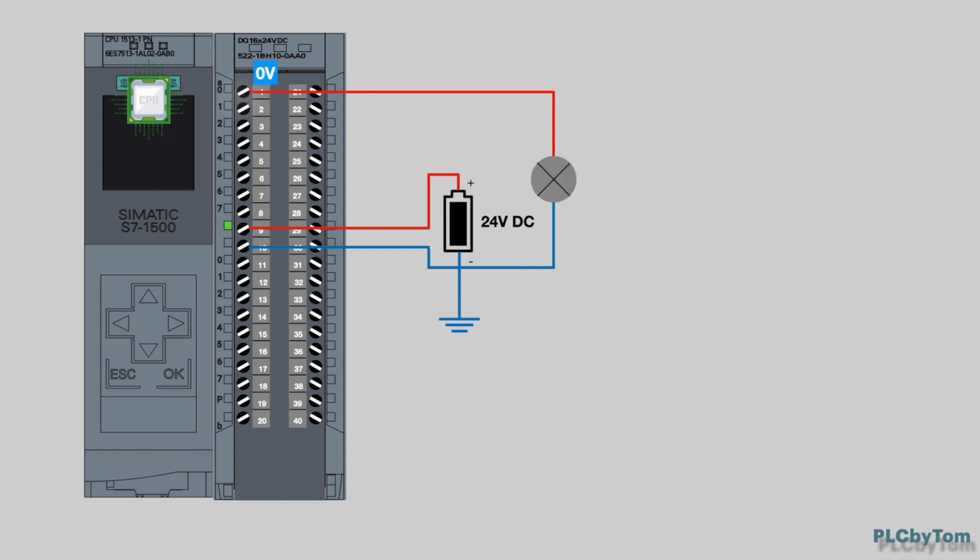Also, there are indication lamps at each channel and it will light up green when output is activated, which gives us the ability to see status of outputs at a glance. Depending on the load of the output device, the output module shall be properly selected. For example, a solenoid valve requires more current to activate than an indication lamp. So due to this, consider what the output channel load is before connecting to it.